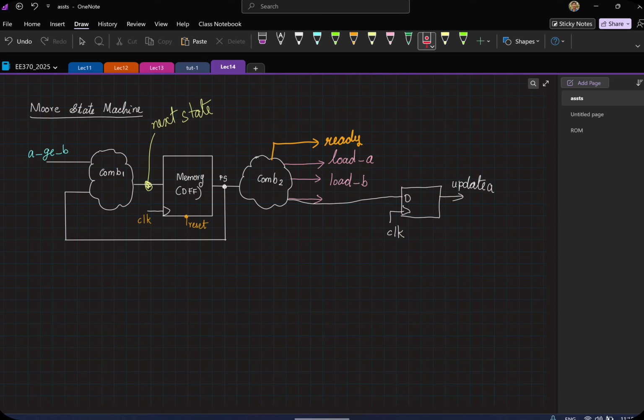So now let me ask you a slightly different question. Would you consider clock and reset as inputs to this FSM? Right? If I sketch like this, it is reasonable to not assume clock or reset as input to the system. Now, if I had a synchronous system, wherein synchronous reset, meaning the reset is not given here, I give the reset also as input to the D side.